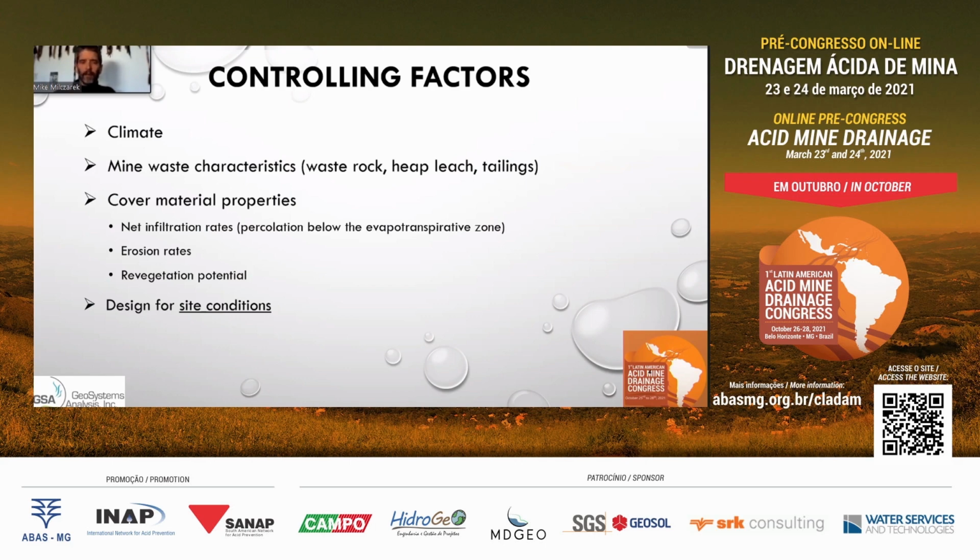These affect the design, both in the case that if you use an ET cover system, the waste becomes part of the cover system and affects the performance, as well as for tailings, which experience variable consolidation. You have to have different considerations and possibly different designs for different materials.